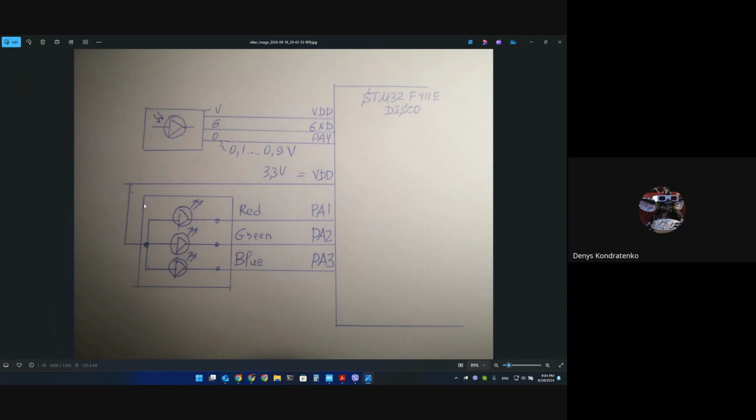We have a 3-color LED component. It's present here. And as you know, we have the 3-color LED with common anode. This anode line would be connected to the 3.3 volts. We will provide voltage from the STM board. So positive voltage here. It means that if we want to enable the respective LED, we need to create negative voltage here, 0 in our case.